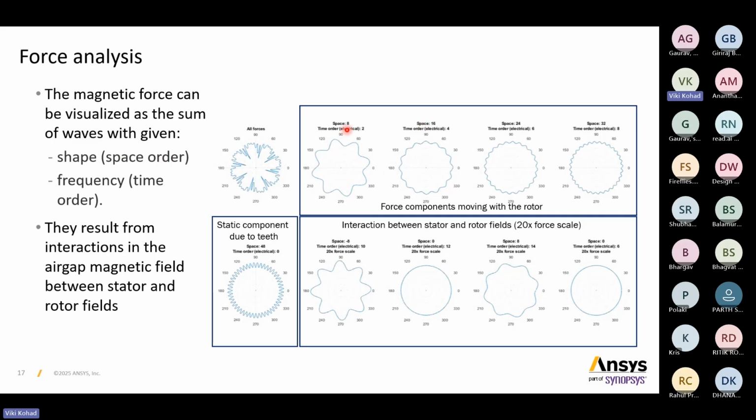You can see space order 8, space order 16, and this is the time order, which is based on the frequency, and this is the shape you can see. These are the force components, the radial force components of the motor, that you can see here.